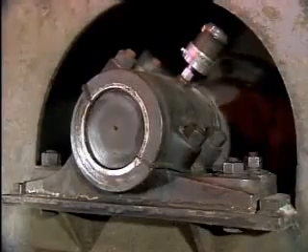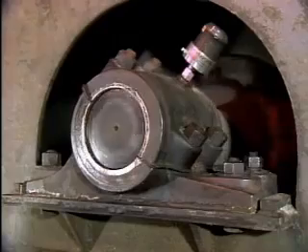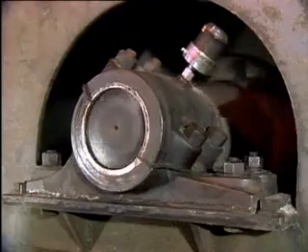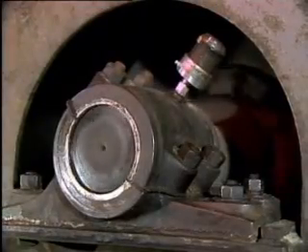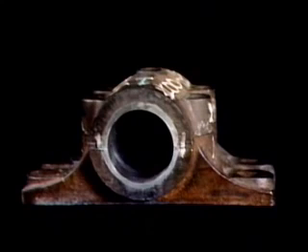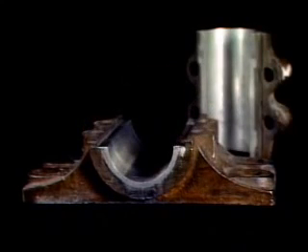It's also called a journal bearing because the part of the shaft that rides inside the bearing is known as a journal. A journal normally rotates on a lubricating film of oil or grease. The lubricating film separates the journal from the bearing surface. This model has the housing and the bearing in two parts. Sleeve bearings are usually made of a very soft metal so that the bearing surface will wear before the journal. It's much easier and cheaper to replace a worn bearing than to replace an entire shaft.